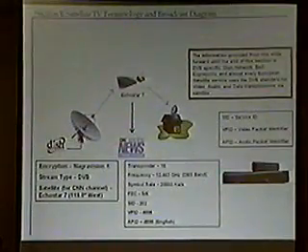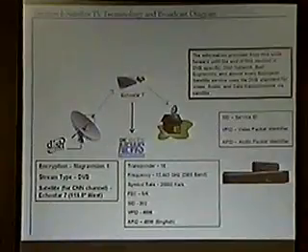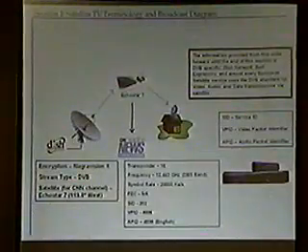The transponder 16, that's actually just not even relevant. I'm just doing this to sort of familiarize with the terminology again. The frequency is 12.443 gigahertz, and all of your receivers know this information. They don't have to search it out and find it, or you don't have to specify it. And this operates within the DBS band. DBS band is just those home services. They operate within a specific frequency range, which is 12.2 to 12.8 gigahertz. And the symbol rate's 20,000 kilosymbols per second.